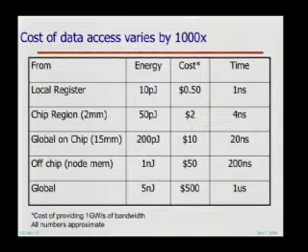So I consider a word to be 64 bits. At a gigaword, basically gigahertz 64-bit transfers through various levels of memory hierarchy. This was a set of numbers produced for 130 nanometer technology, and it scales roughly linearly with technology, not exactly, but close enough. And what you'll see is that reading a register is cheap compared to a floating point operation. It takes about 10 picojoules rather than 50 picojoules for the floating point operation.